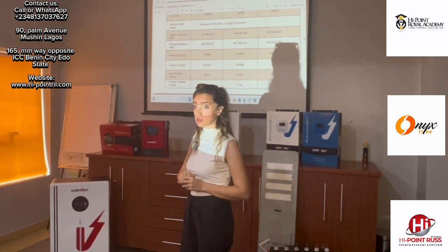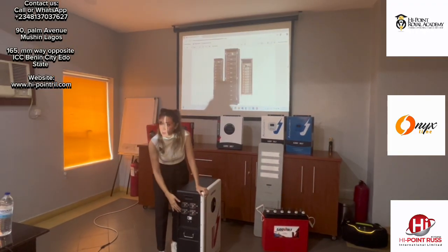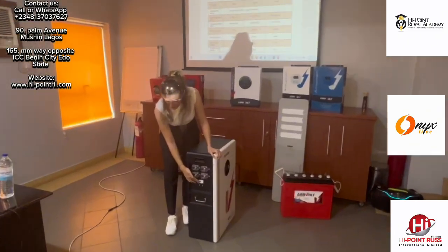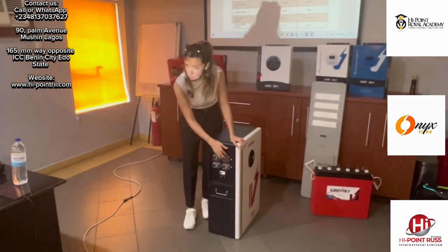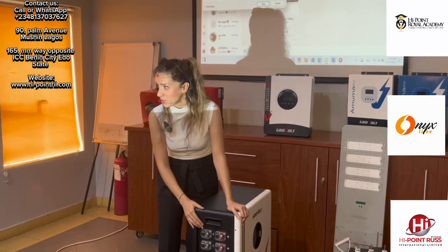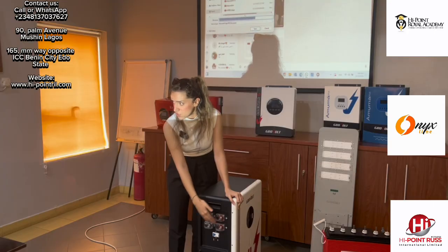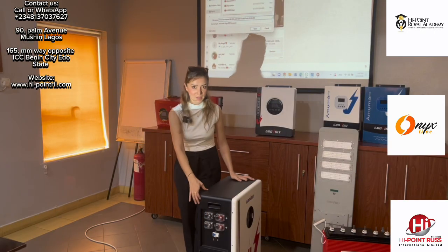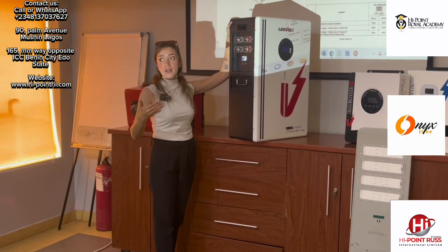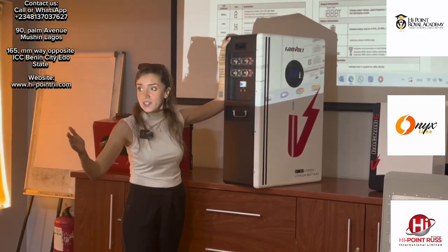Okay, on the battery here we have four terminals and a breaker. The advantage is that if you parallel more than 2 or 3 batteries, you will not need a bus bar box; you can use it from here. We have 4 terminals we can use for parallel because this battery takes parallel up to 16.